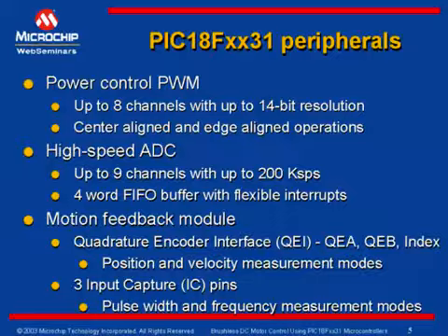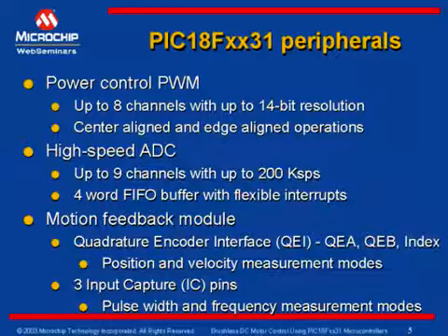velocity and speed measurements. The 3 input capture pins have multiple modes for pulse width and frequency measurements, and this has an interrupt on change feature used for the Hall sensor interface that we are going to see in the coming section when